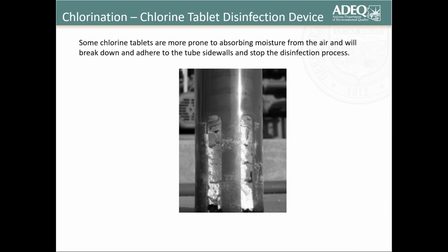And so it makes sense the binder might not be as strong as the 9 milligrams per liter tablet. But that's something to keep in mind, is what type of tablet, and monitor whether it could start having some problems breaking down in the upper part of the feed tube.